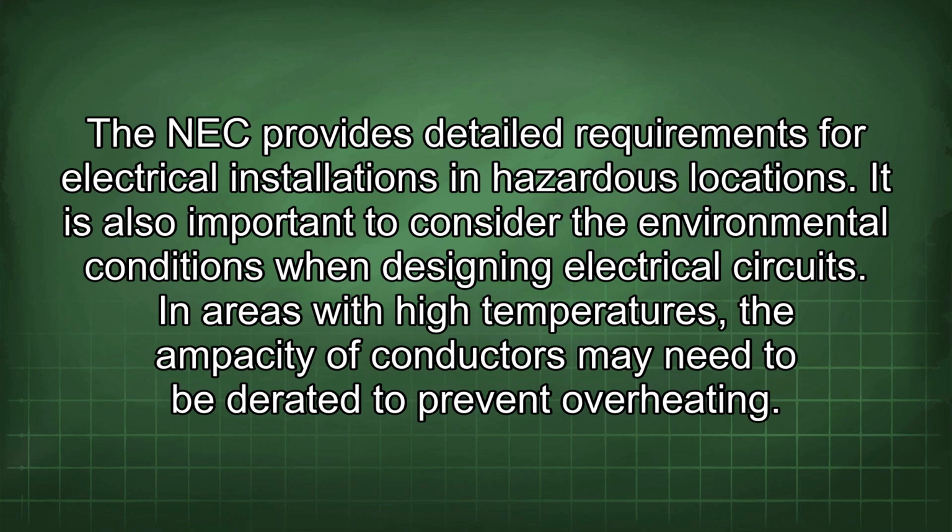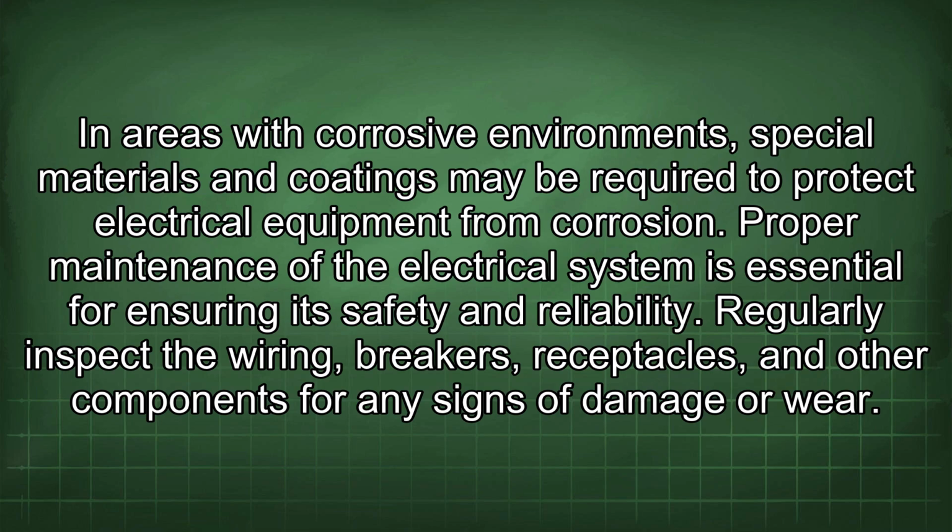It is also important to consider the environmental conditions when designing electrical circuits. In areas with high temperatures, the ampacity of conductors may need to be derated to prevent overheating. In areas with corrosive environments, special materials and coatings may be required to protect electrical equipment from corrosion.